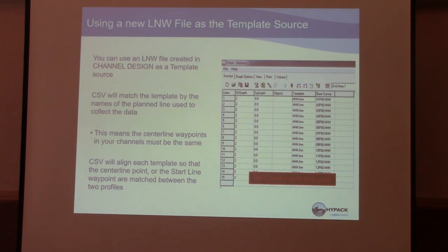You can use a line file created with a channel design, a line file that has embedded templates in it. You can load that as a template, but it has to be the same line file you ran your survey on. It has to line up those start and end points of your channel.